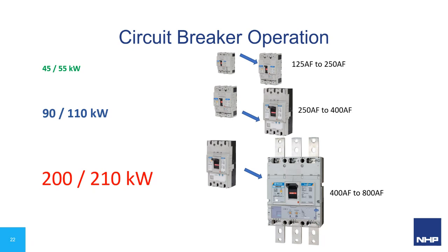The realisation came from trying to go from a 400 amp device to a 630 amp device. Now, these are physically the same device, only with additional contact dimensions, things like surface area and silver and other bits and pieces and current carrying capacity within the circuit breaker. The 630 amp device we tested was an electronic breaker. So initially this breaker was successful in not tripping. However, after a number of DOL starts on site, the breaker developed an internal arcing fault that rendered it inoperative.